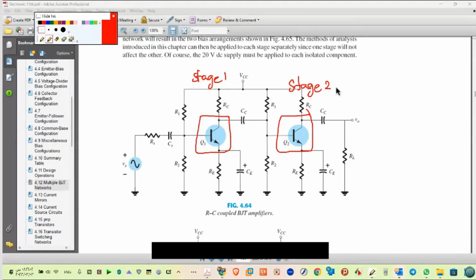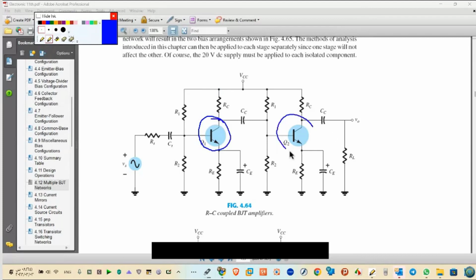Okay. Why do I need two transistors, not one? For example, I have a small current or small voltage here. I want to increase this one. Can I increase it with just transistor 1 with beta equal 1000? Yes, we can. But for this reason, we need a special transistor and a big transistor. And the most important thing is temperature. The temperature will be very high for this transistor. So instead of using one transistor with beta 1000, I will use two transistors, transistor 1, transistor 2.